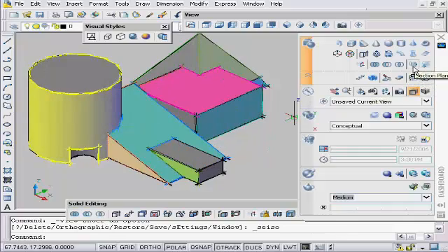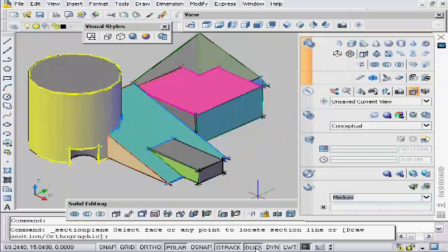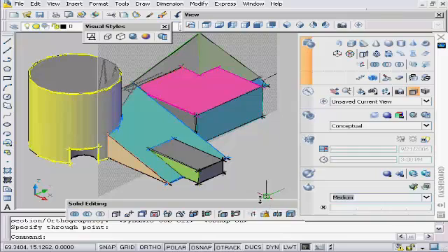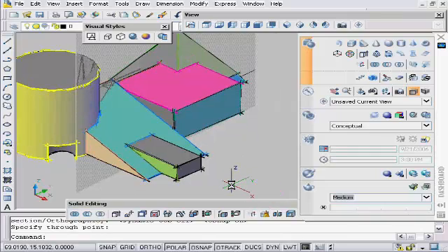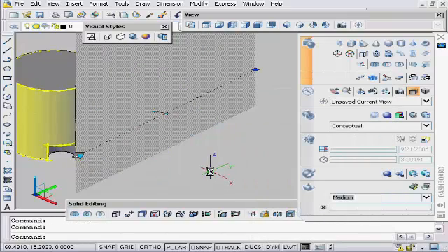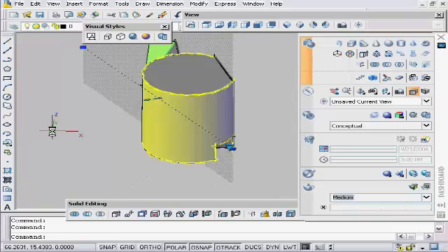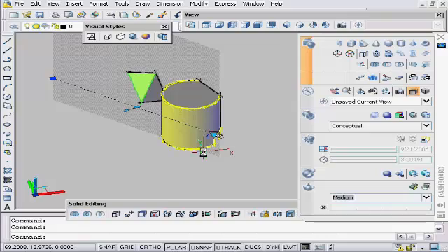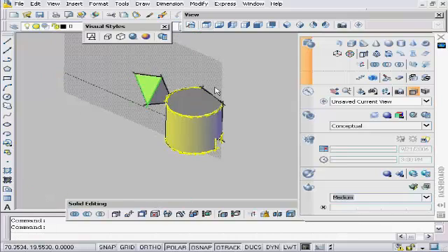Okay, go back to my section plane again. This time I'm going to turn my DUCS off. Now none of my faces are going to hover, so now I can maybe use F3 as an object snap and just click on there. Now I've created a section plane there. I can hover over it, click on it, right click, activate live section. There's that live section that I can shift middle mouse button, look around, and it disappears and comes back.